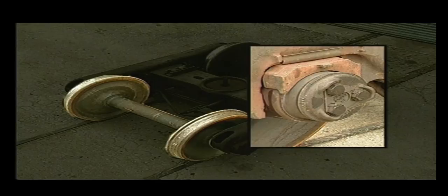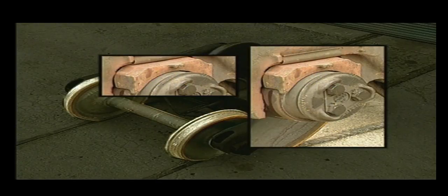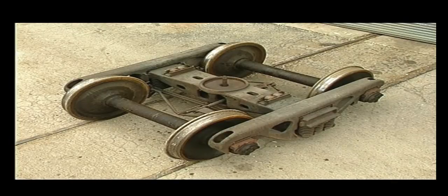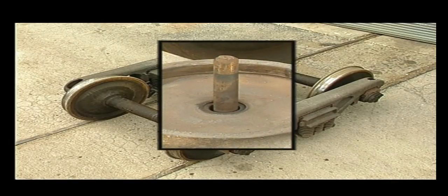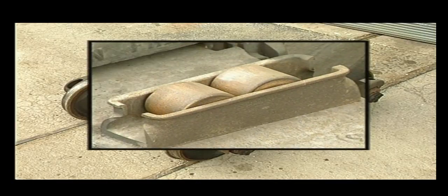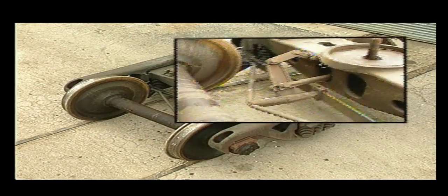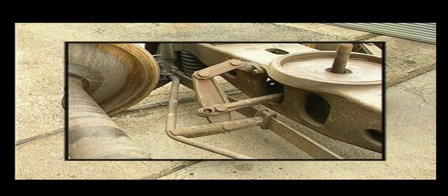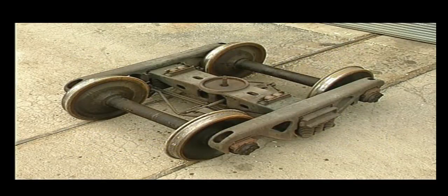the wheel and axle assembly, including the roller bearings, which allow the tank car to move and guide that movement along the rails; the bearing adapters, which provide a mount for the roller bearings to the side frames; the center pin that guides the center plate into the center bowl of the truck bolster. Side bearings provide support against rocking the car body while in motion. And finally, the brake components, which will be discussed later. It should be noted that these are the most common components of a truck assembly. Some designs may be more complex.